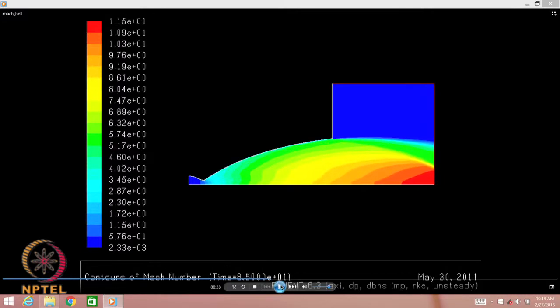Now, the contour, the exit is smoothly out of the nozzle. You have nice Mach number contours which are continuous. So, you have this P critical 3 now. Any pressure between P critical 3 and P critical 2 is overexpansion, but in today's class we are going to discuss the back pressures between P critical 1 and P critical 2.